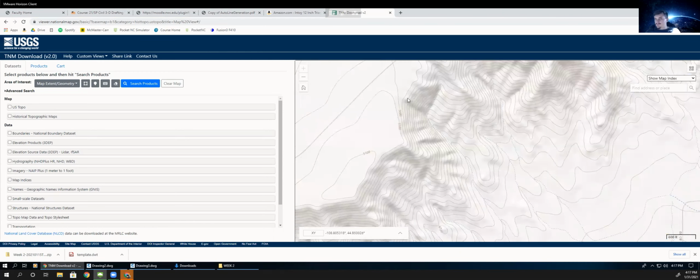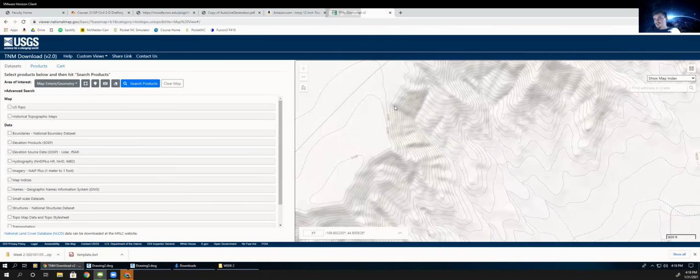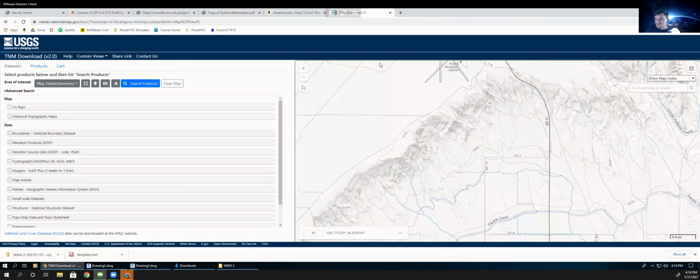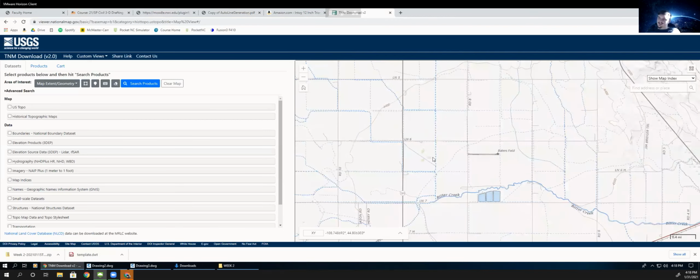So this is just kind of zooming into the bench. It looks like 5,080, 5,100. So between this line and that line, there's 20 feet elevation change, okay? If you think about how close these are, that's 20 feet, 20 feet, 20 feet. So you're dropping pretty quick right there. Whereas if you actually look in town, you hardly see many changes on these topo lines.